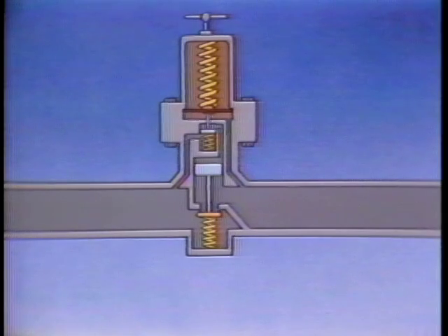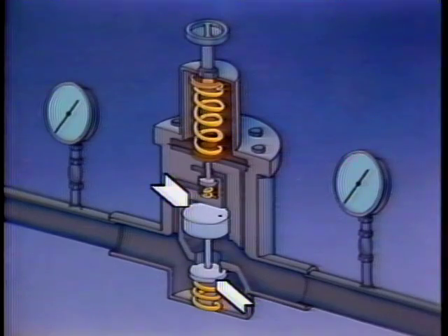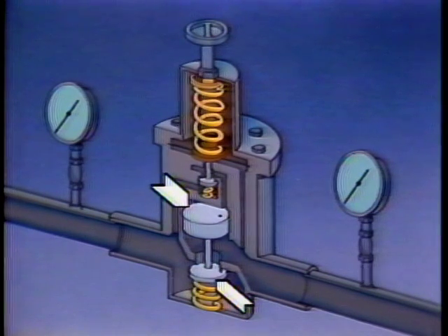The pilot-operated PRV has two distinct advantages over the direct-acting type. First, the short travel of the pilot valve allows the use of a metal diaphragm suitable for high-pressure service. Secondly, the relative difference in size between the main valve and the piston operator serves to amplify the control signal. This amplification allows the main valve to open easily against high pressure because even though the inlet pressure opposes opening of the main valve, the amplified control signal of the controlling piston provides enough force differential to easily open the valve.